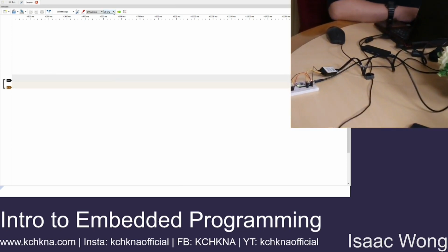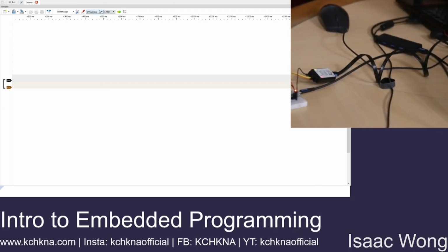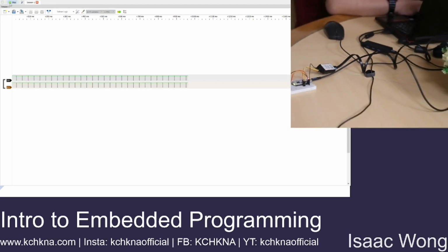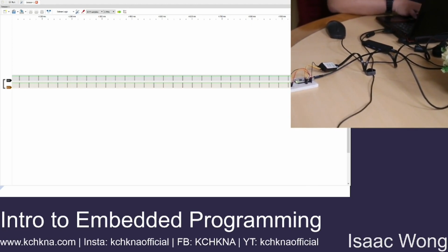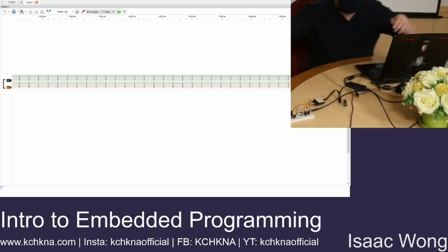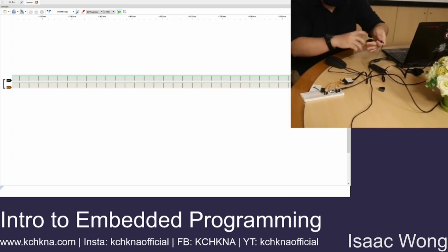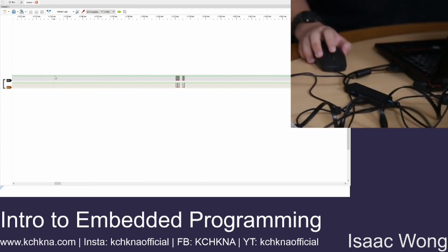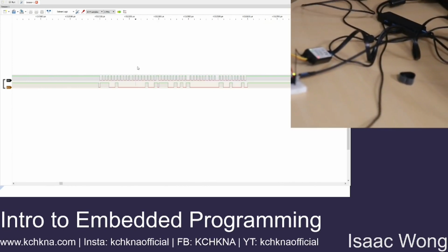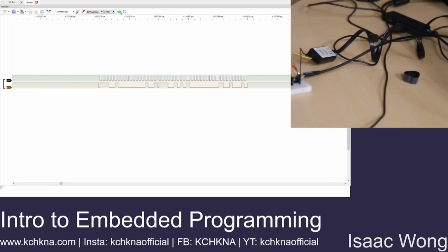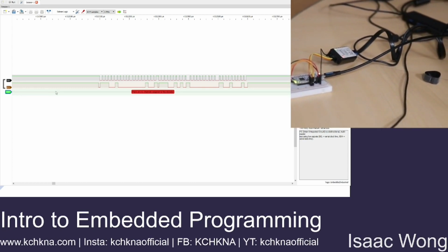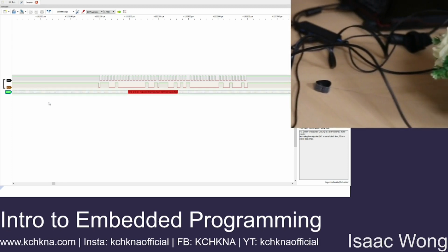All right, so you can see all these are the packets that are actually being sent by my microcontroller. You can't possibly read this, but the logic analyzer has decoders for protocols. So I'll just turn on the I2C decoder. Now I need to tell it which line is the clock and which is the data line. So I'll just put it like that.